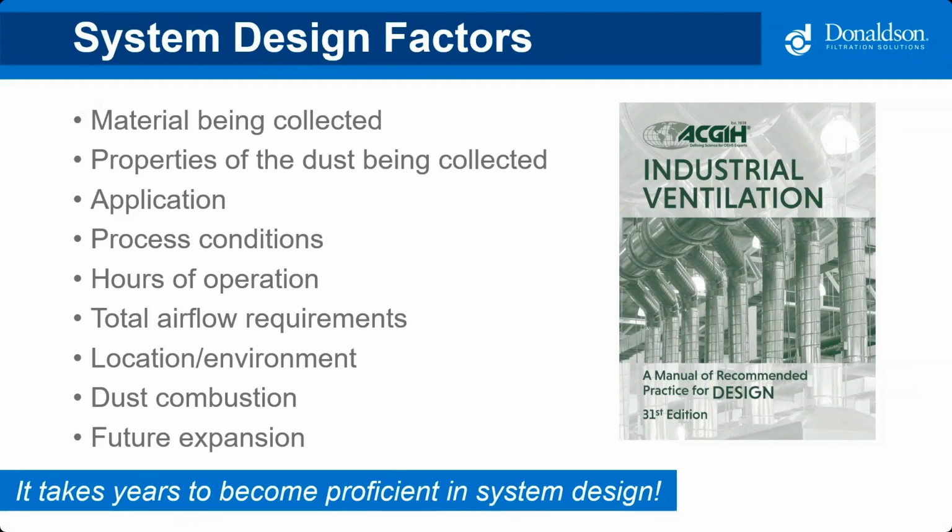Things that we need to consider when designing a system include the material that's being collected and the properties of the dust being collected, the application being utilized, and the process conditions. Is it humid? Do the workers use personal fans? Does the facility have conditioned air? What are the hours of operation? Will the system be used continuously or intermittently? What's the total airflow requirement? What location or environmental restrictions exist?